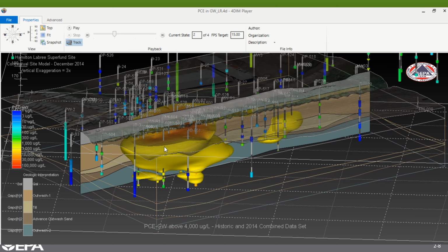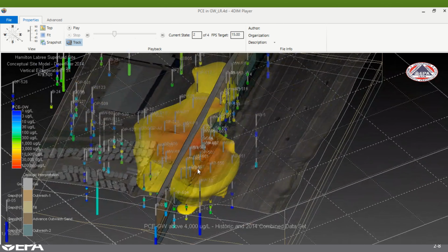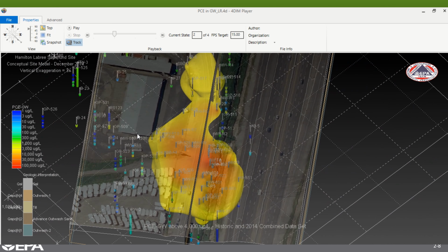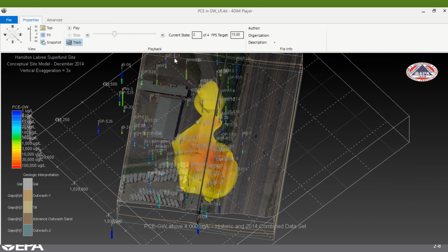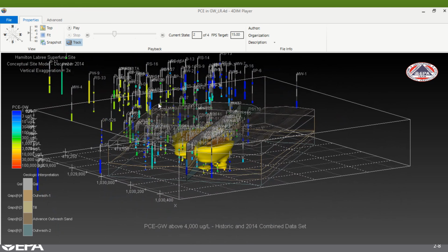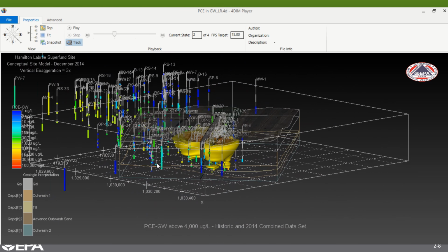and that is really going to help as we move towards not only focusing here in the source zone for thermal, but understanding some of the higher concentration and higher hydraulic conductivity transport pathways out in this zone, and over here on this side of the site looking to do injections and placement of a barrier for enhanced reductive dechlorination, taking advantage of that residual heat from the thermal system, which will be placed in this area. But we can do the same thing with the historic information, but you can see with all of this information, it is significant.